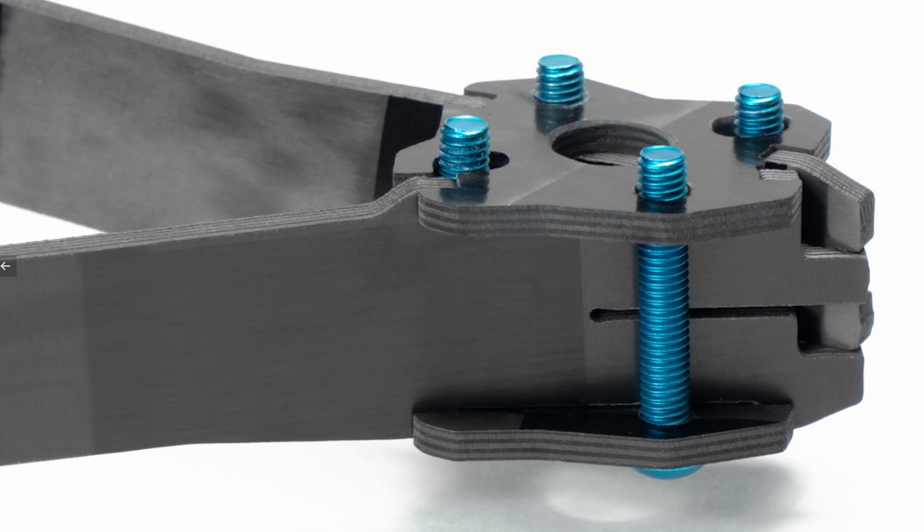So you were talking about the stiffness of the frame, right? Yeah, exactly. Because the stiffness and the weight is what's affecting your resonance frequency. A higher weight will lower your resonance frequency. A higher stiffness will increase your resonance frequency. So you want as high stiffness as possible with as low weight as possible. But the problem with high stiffness is that when you crash, it's brittle. You're more likely to break.